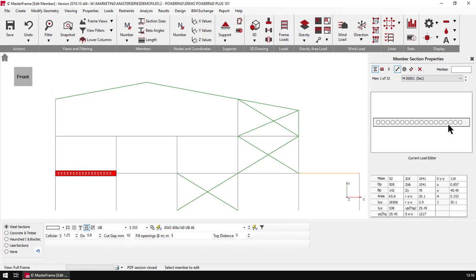I could go for some cellular form beams, which means that the beam becomes a bit deeper. It jumps from the 406 up to 509 deep as being the standard castellation, and we're going to go for, I prefer the openings, 1.35 spacing in that cell form beam.